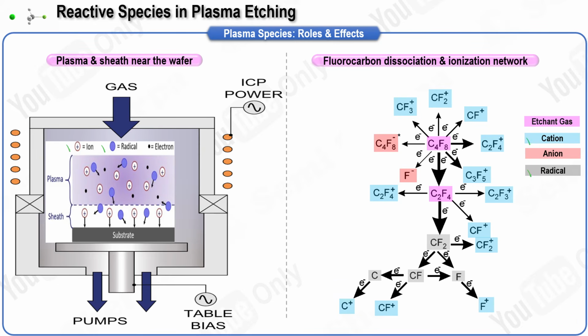They are also used to mitigate electron shading and differential surface charging by helping charge neutralization during the plasma off period. Representative anions are Cl-, Cl2-, F-, and CCl4-. In the bulk plasma, electrons sustain the discharge by impact excitation, dissociation, and ionization. Radicals are created in that process and then diffuse to the wafer with little momentum but with high chemical reactivity.